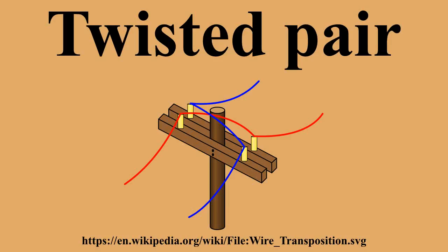Disadvantages: deformation. Twisted pairs' susceptibility to electromagnetic interference greatly depends on the pair twisting schemes staying intact during installation. As a result, twisted pair cables usually have stringent requirements for maximum pulling tension as well as minimum bend radius. This fragility of twisted pair cables makes installation practices an important part of ensuring the cable's performance.